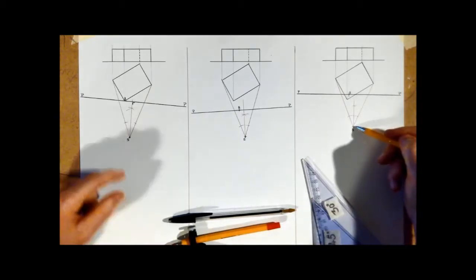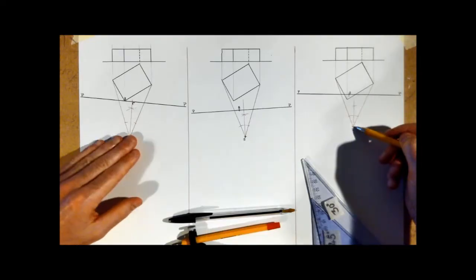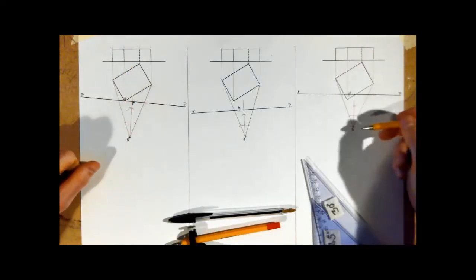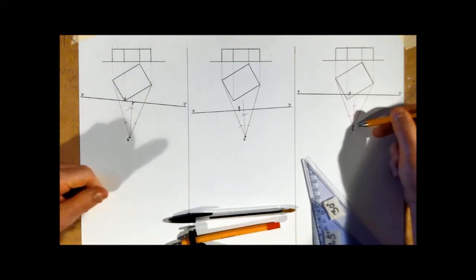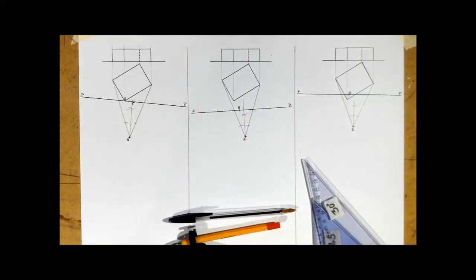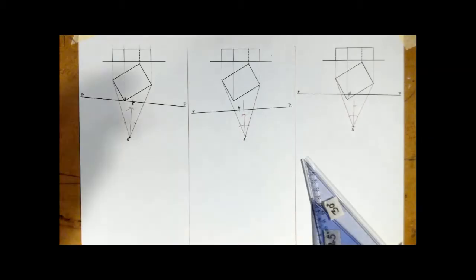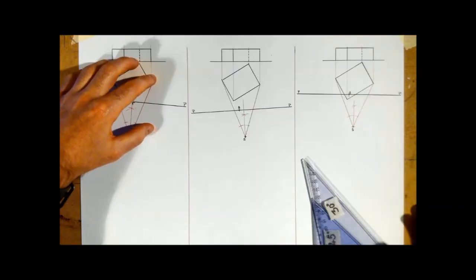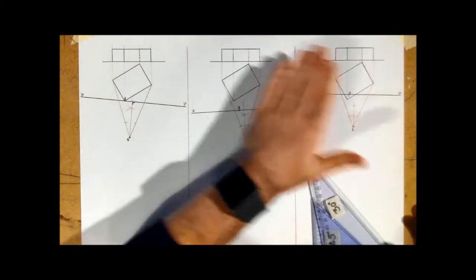So in this view, in comparison to this one, we're going to see this one being a lot smaller in comparison to this one where it's going to be closer. And the reason it's closer and it's going to be bigger is because the spectator is standing closer to the object. Okay, now the next part of the question would be setting up our vanishing points and our ground line and our horizon line. Ground line, horizon line first, and then the vanishing points technically. Now, to be able to do that, I'm going to start it on this one, and then once again fast forward on these 2 over here.